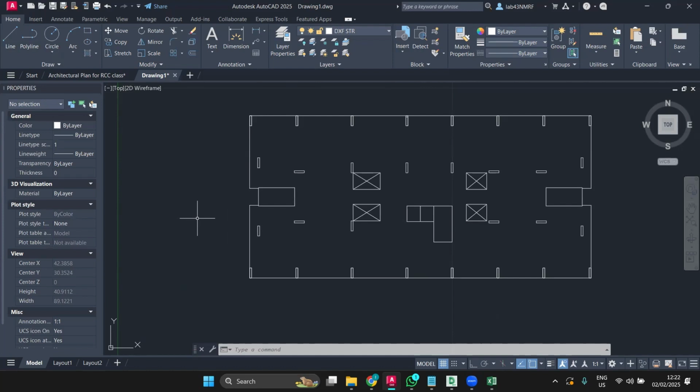You're supposed to keep it in the shorter direction first, because the width is less. In terms of displacement and drift, this will affect more than the other. This side, on the major axis, if it goes, the whole building has to go. Either way, you still need some sort of stiffness.